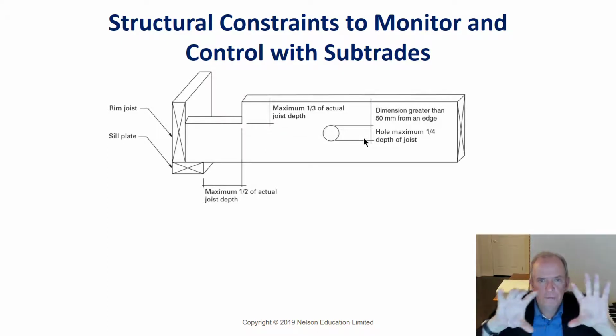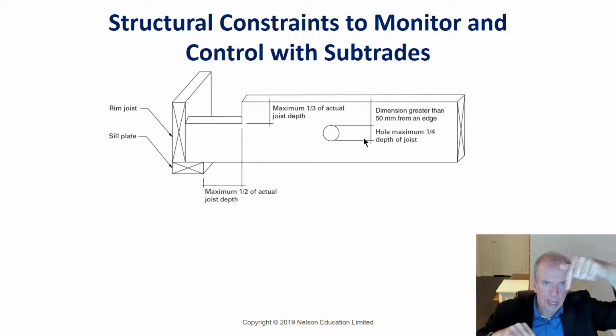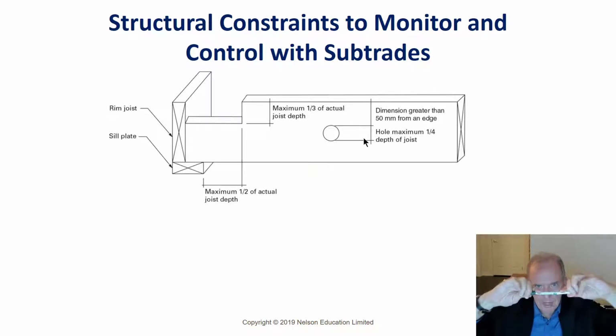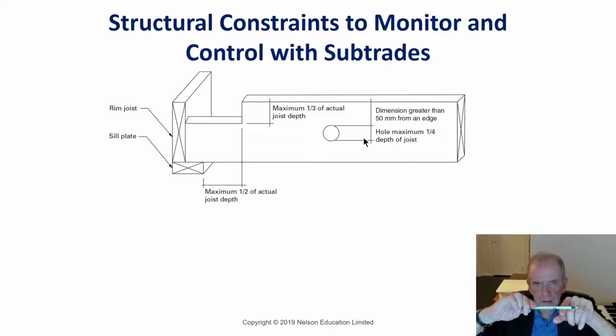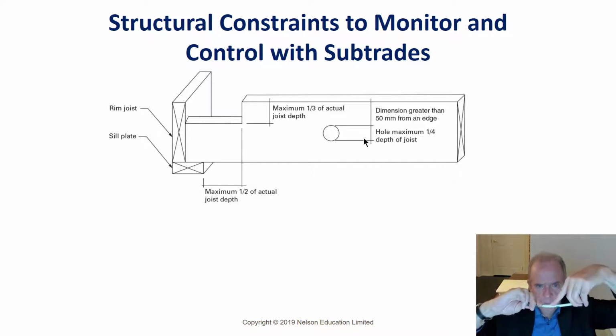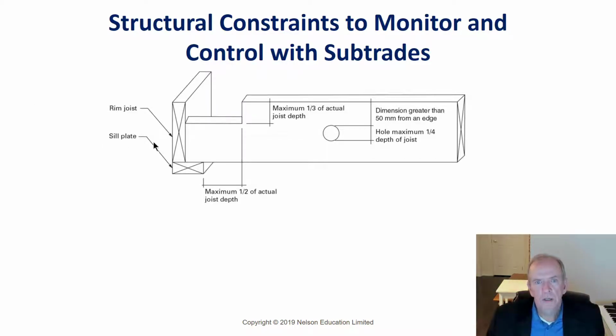that when you think of a joist and you have a load coming down on it, it pushes the joist down. So I want you to imagine that, or take a pen or a pencil, and when I put a pressure on that pen, what kind of force is on the bottom of the pen? Is it compression or is it tension? Force going down. If you said tension, you're right. On the top of the joist, what kind of force would be on it? If you said compression, you'd be right. So in the middle, it's more or less neutral.